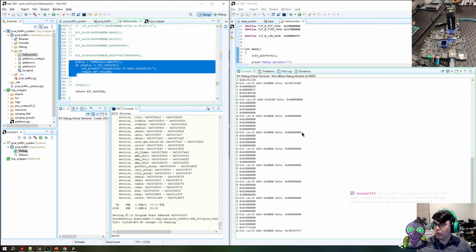That's a great thing I wanted to try. So the R5 processor has access to the PCIe device, right? So theoretically, we could pass something down to the R5, and the R5 could use low-level access, DMA, real memory, physical memory addresses to probably speed up your PCIe communication.